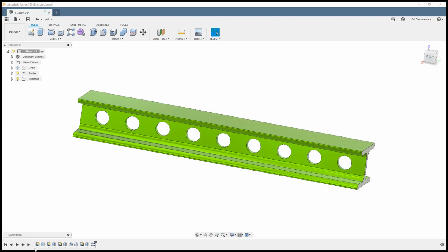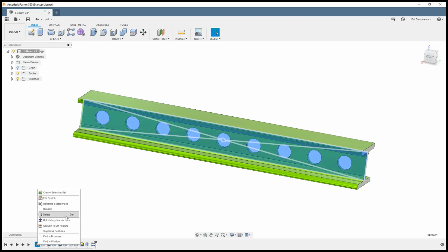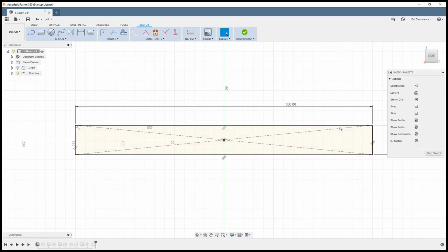So then what you want to do is come down here, find the sketch that you want to affect, and then this value right here, just like we were doing with the formulas, you go to edit it. Now there's nothing here to click on, so you just start typing, and this is kind of the beauty of this. That was called length. So we just hit L and it says, hey, look, there's the length parameter. If you had many different parameters in here, if you type the first letter, then it'll alphabetize it. If there's just a few, you just hit any letter and they're all going to show up basically. So you hit this, it says length, and you hit enter.